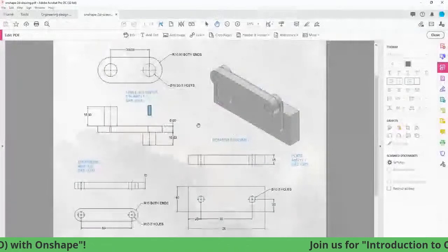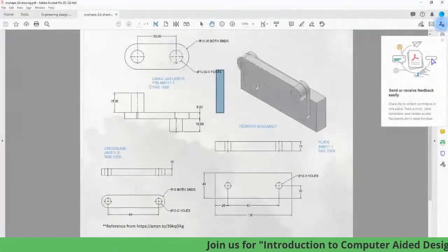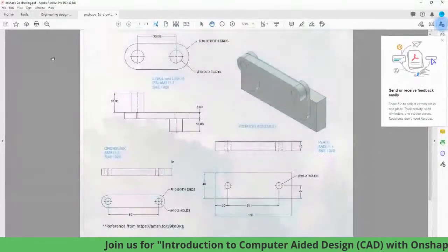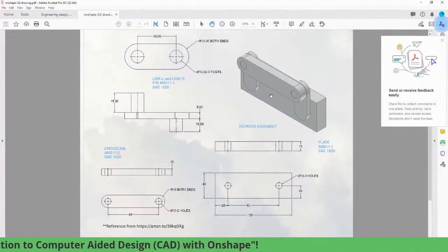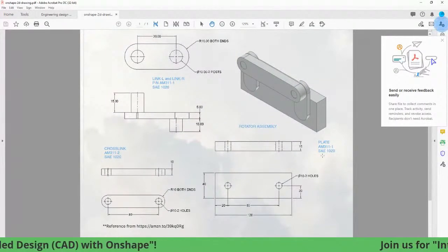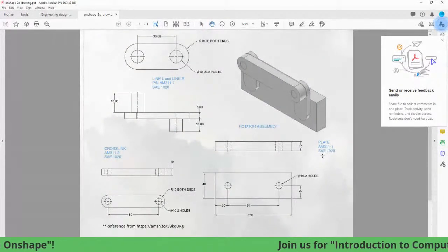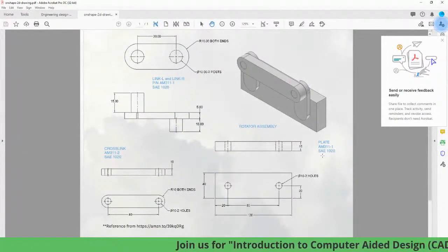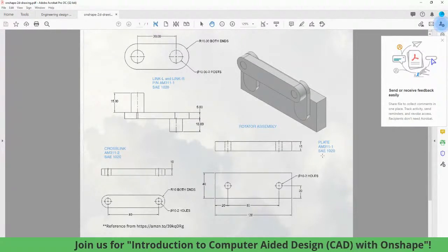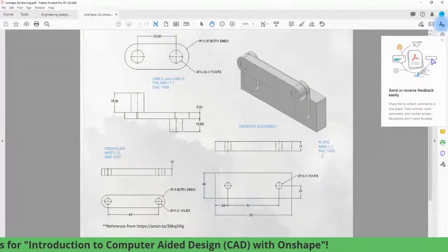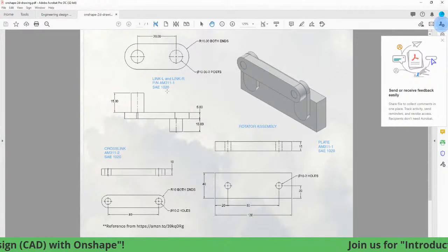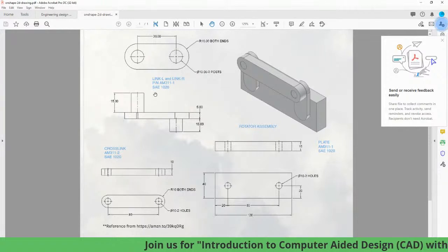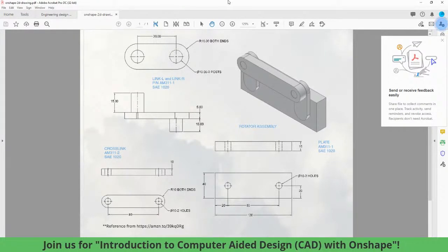Okay, so notice this assembly. What I am seeing here is that the two parts are referencing this part over here, which is named the plate. With that in mind, we have identified our parent component, or part, which is the plate. As a personal preference, I prefer creating the plate right away, or any of the three will do. But for this session, I prefer the plate.